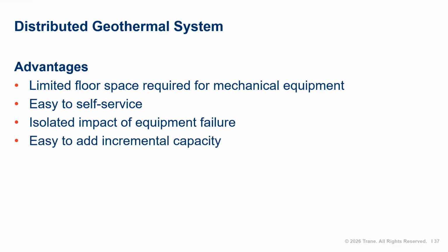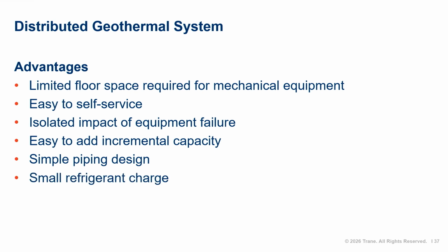And capacity can be easily added and incrementally funded, assuming, of course, that the borefield was sized for that added capacity. The piping design is relatively simple, and the refrigerant charge at each heat pump is relatively small, making it easy to comply with safety codes.